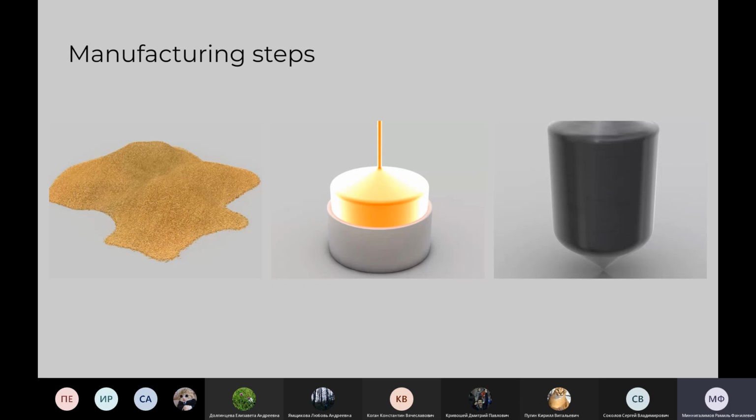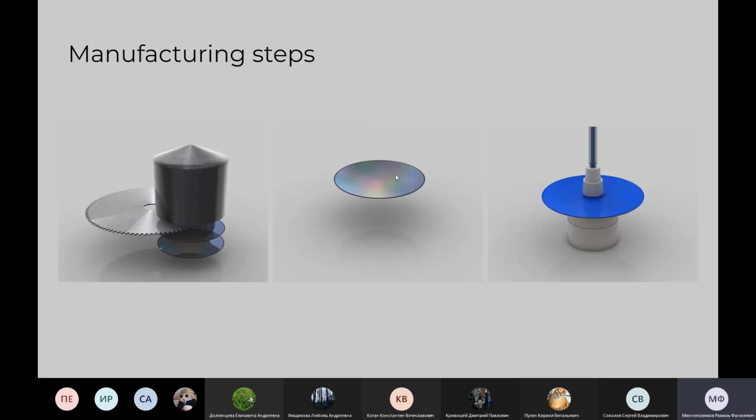After this process, silicon melting is performed, and the result is a single crystal block, a monocrystal. It's called an ingot. Single crystal blocks are produced from silicon at the electronic level. The block weighs about 100 kilograms and has a purity very close to 100%. Then the single crystal block will be cut thinly into semiconductor disks, called wafers. After the cutting phase, these wafers will be polished until they have a smooth surface.